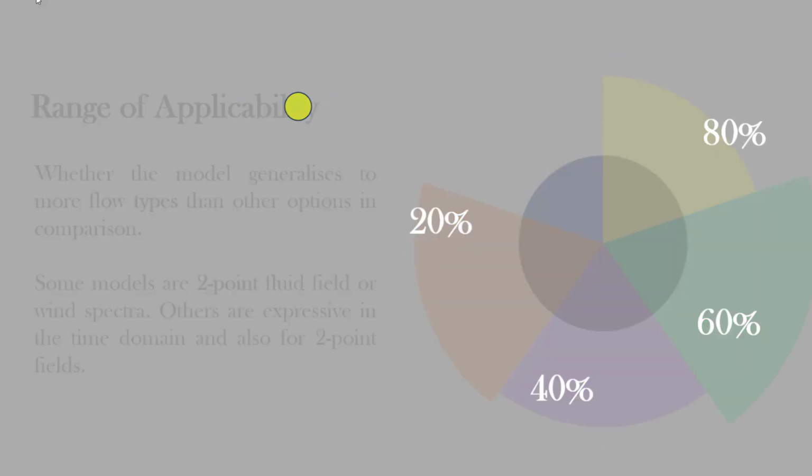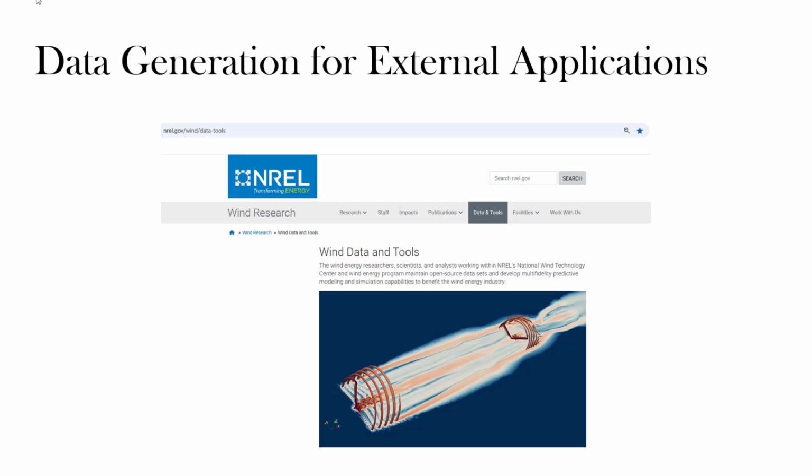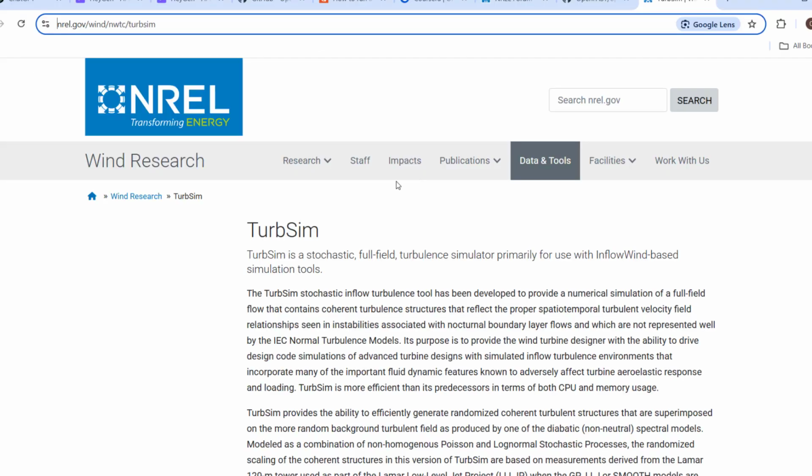So there are several data tools that can be used to generate information for either OpenFAST or for other programs. For example, you can use the HydroDyn module to generate data for a different program. Probably you want sea state data for a different software. You can use any of these simulators to generate that information that you need.